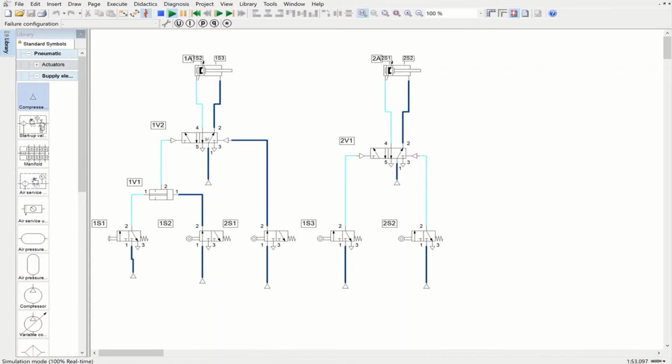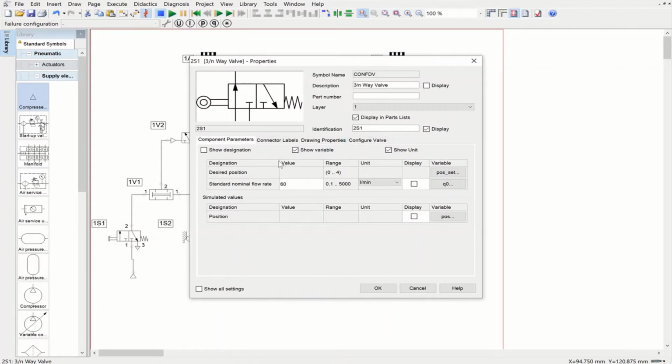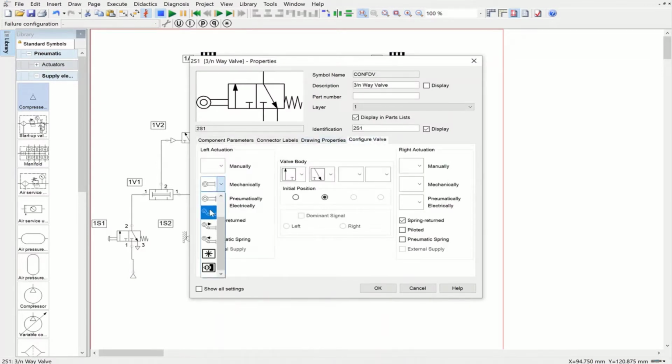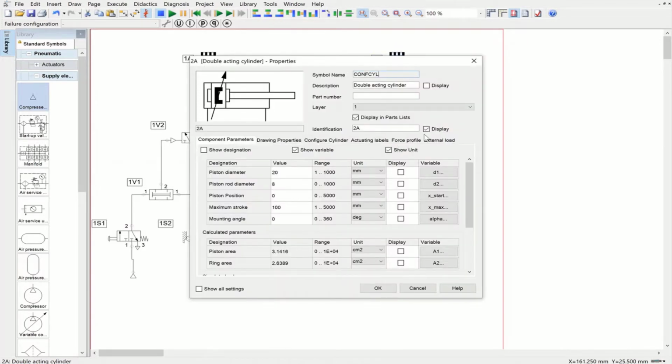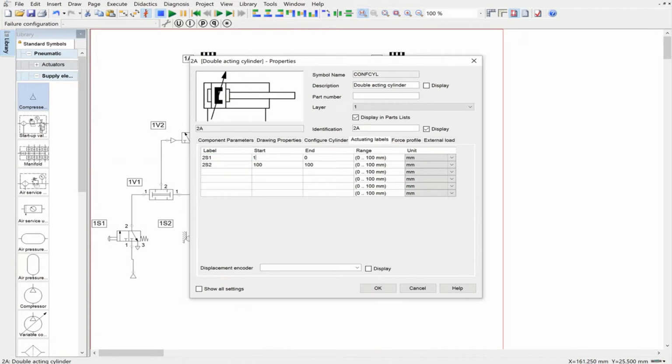In order to avoid this first signal overlapping case, we have to remove this form of actuation that we have. We have to update and use another one. So let's pause it, and I'm going to change this one to the form of this valve, this actuation, and then hit OK. Now this 2S1 is connected to the fully retracted position. This time I'm not going to consider that 0 value, fully retracted position. I'm going to look at a bit before, so I'm going to choose 1 millimeter for that. So let me put 1 millimeter here, and that is 1, 2, and hit OK.